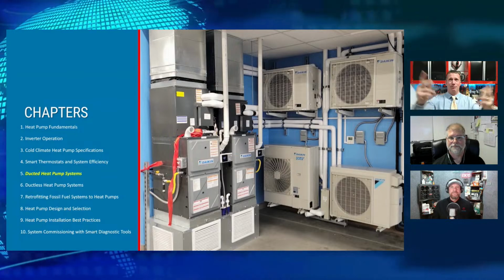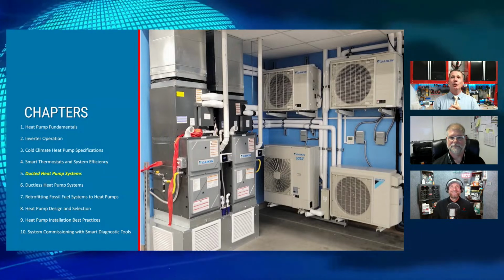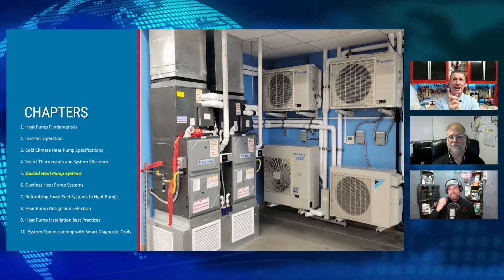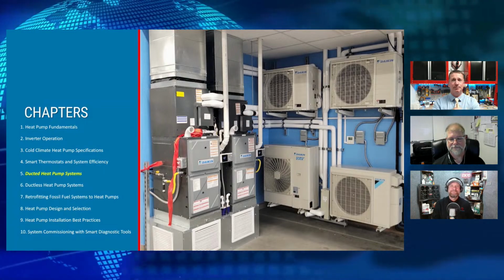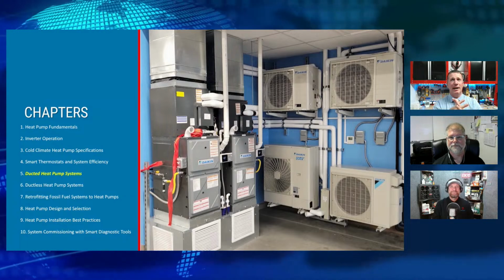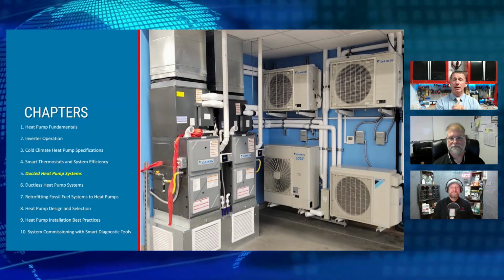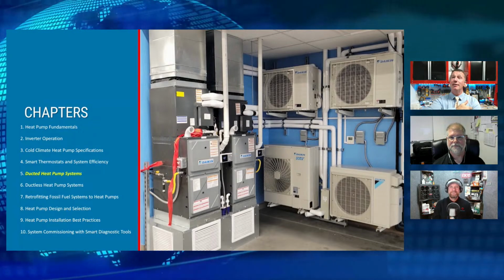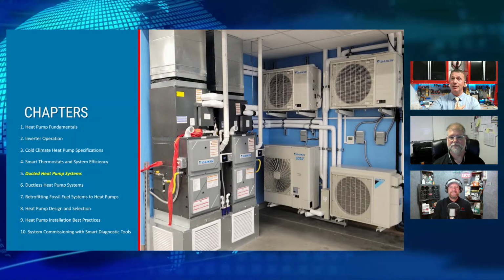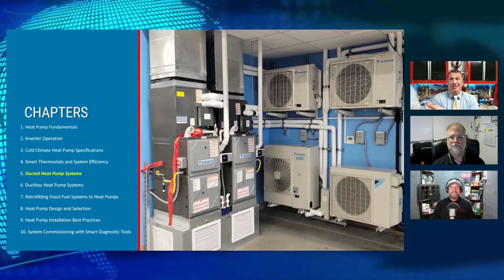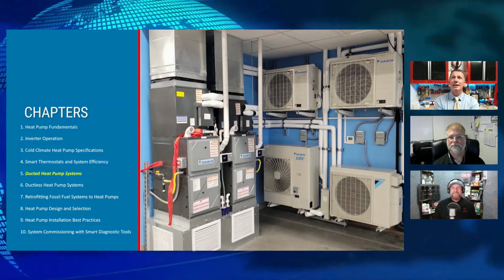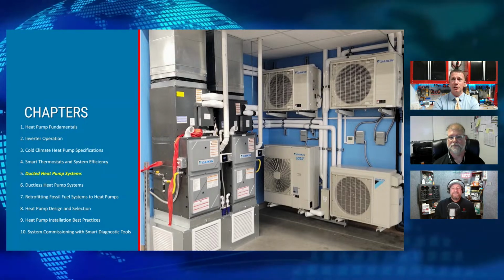David, let's assume that I've got a newly installed inverter-driven system, and I haven't paid as much attention to airflow as I should, so I've got poor airflow across the evaporator. What is a primary driving force for an inverter from that outdoor unit? Think about superheat, right? A lot of our units are being driven by superheat and compressor discharge temperature.